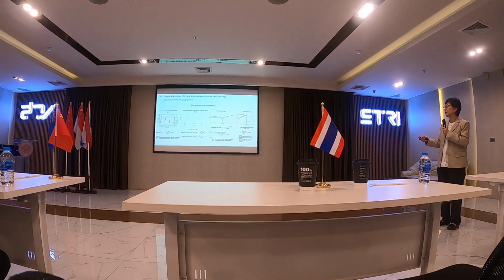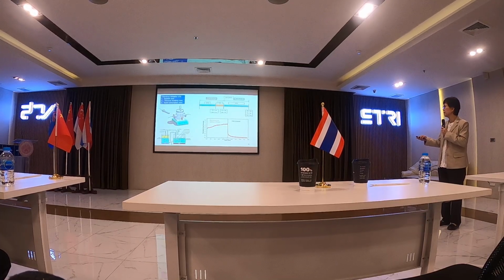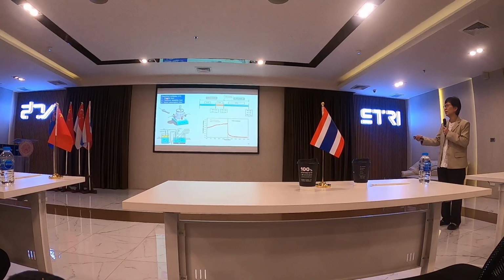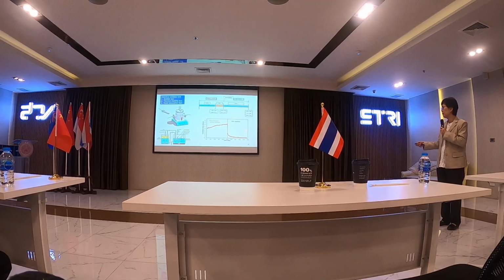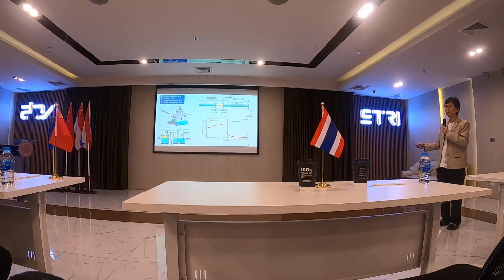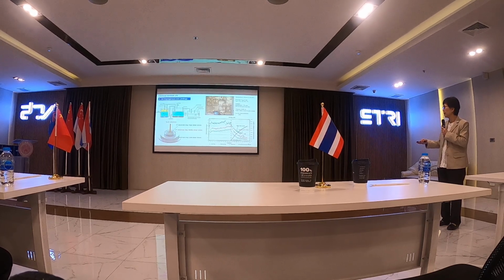For chemical inhibitor testing, we now use different types of techniques. For example, this one, the normal inhibitor testing for oil and gas, is a bubble test, thermal stability test, and sand absorption test. This is the test for 48 hours. Here we do it without inhibitor, and after we add inhibitors, corrosion becomes lower. And then this is a jet impingement test.